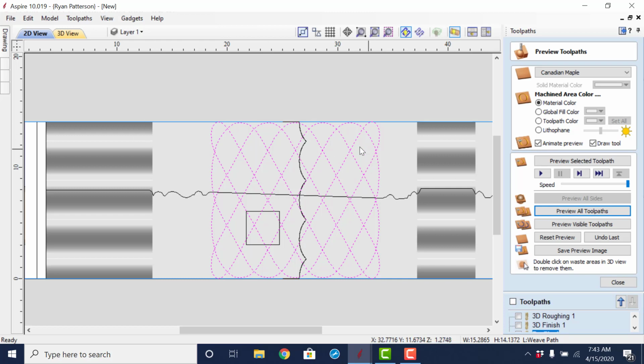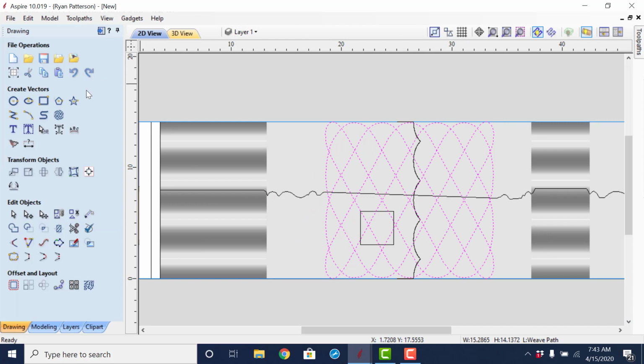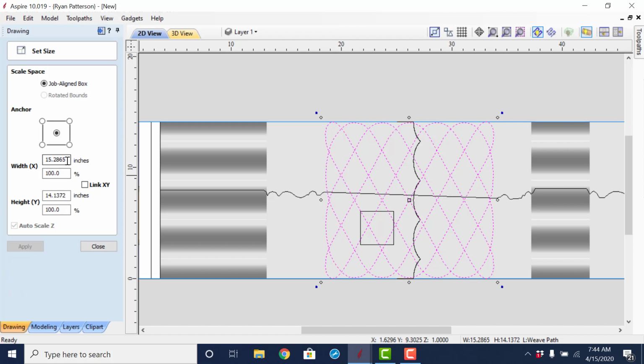So what we're going to do is, with that selected, come over and click the toolpath tab. We're going to scale this back down to half the size of the Y. And again, we could bring out a calculator and do the math, but I could just do that divided by 2 and then hit the equal sign. It's going to do that math for us.